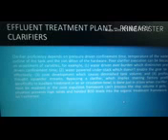The clarifier efficiency depends on the hydraulic detention time, the temperature of the water, the design of the tank, and the condition of the equipment. Poor clarifier performance can be due to a variety of factors. For example, number one, hydraulic overload, which reduces hydraulic detention time. Number two, hydraulic under load, which does not enable the equipment to work effectively. Number three, sludge buildup, which causes reduced tank volume.